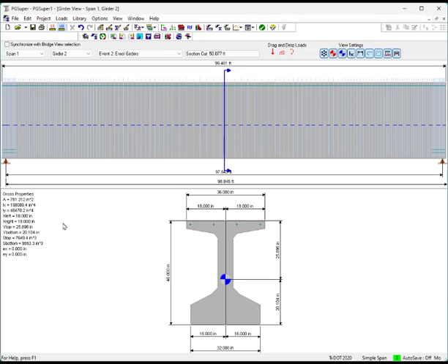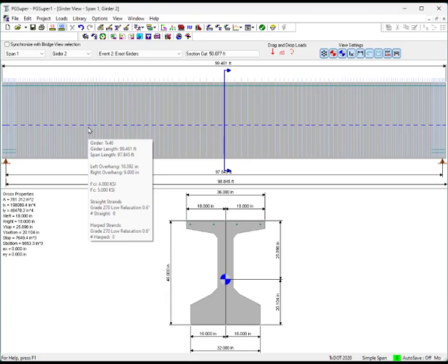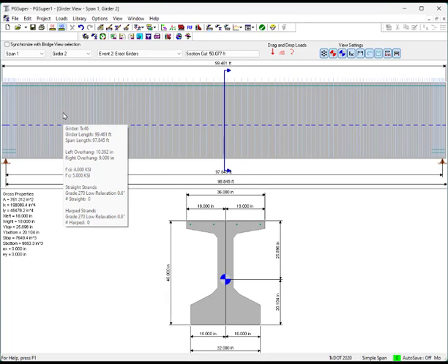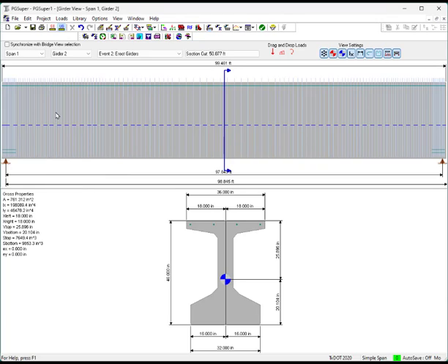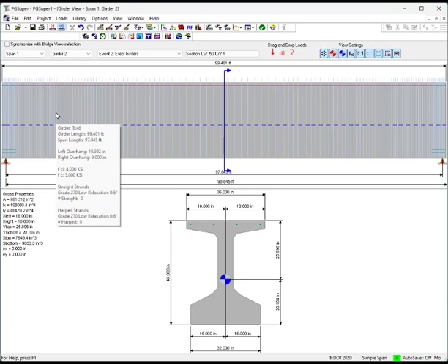The mystery here is pretty simple. As we saw before, our piers are laid out at stations along the alignment, and typically this is at the center line of piers. So we know that girders don't go butt to butt from pier to pier, and also bearings aren't located typically at the center line of a pier. So the answer to the mystery is connections. Connections are at pier locations.